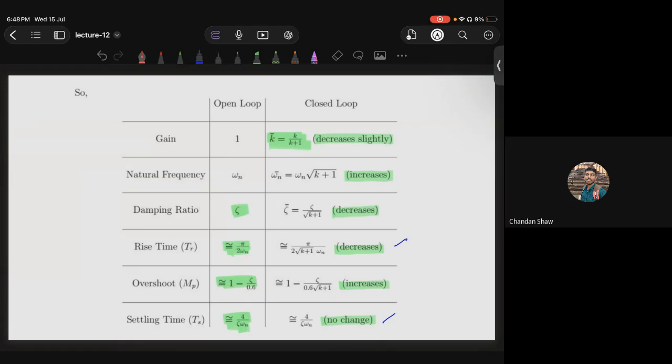It increases the overshoot, and ultimately it introduces the steady state error. That is one point. The second point is overshoot also increasing. So these are disadvantages. The advantage is that it reaches the closer value very fast.